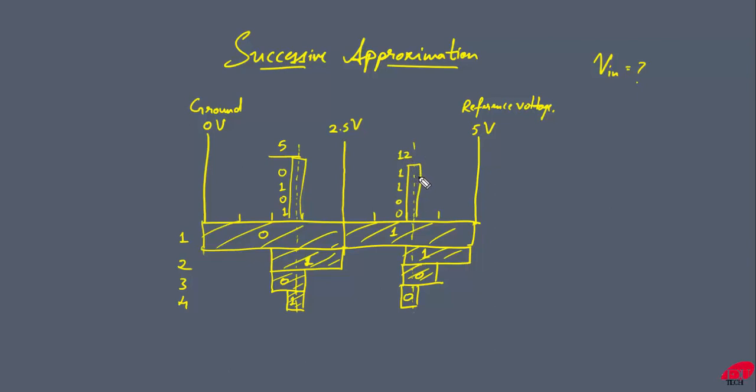Now these are the output bit values that we are getting after converting. But how do we convert these values into appropriate voltages? What is our range and what is the resolution of this ADC? This is a 4-bit ADC. So the 4-bit conversion of 0 volt would be 0000, and the maximum 4-bit conversion, for 5 volt, would be 1111, which is 15.